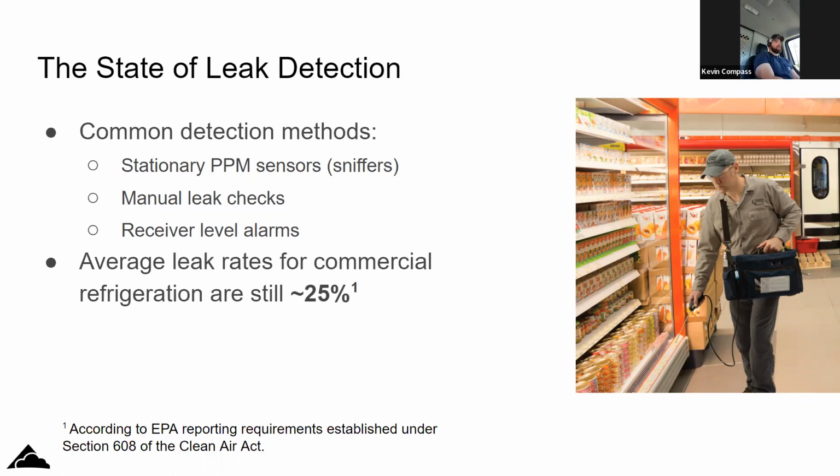I think if they started putting them up higher, there would be a lot less nuisance calls. I know that they say the refrigerant's going to settle on the floor because it's heavier, but putting them up a little bit higher would prevent them from failing so much, I think. In a machine room, they're great though. They generally will, depending on where it's at, as long as it isn't right next to an exhaust fan, will usually pick up a leak pretty well.